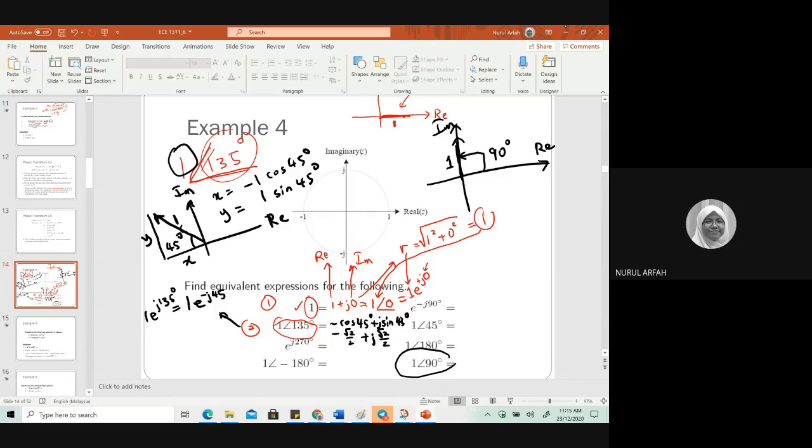And then what is this in rectangular form? Do we have any real axis? No, so it should be 0. And this is positive imaginary axis, so a plus. Then J with what? Is it 90 or just 1? It's 1, because you have imaginary at that side. So it should be plus J. And then in exponential, this will be E J 90 degree, and the amplitude is 1. Okay? Okay or are you confused?